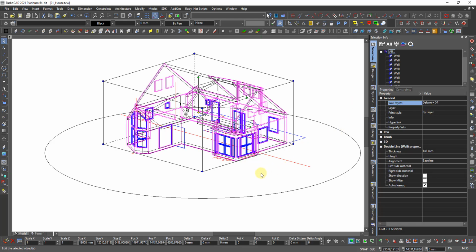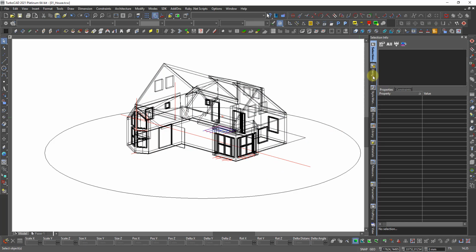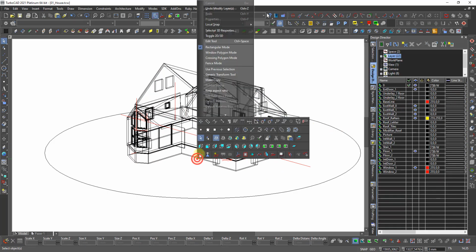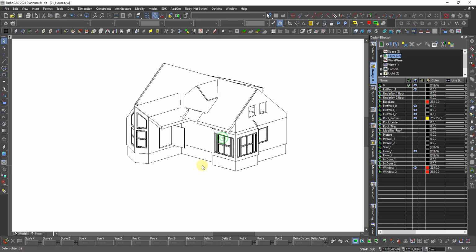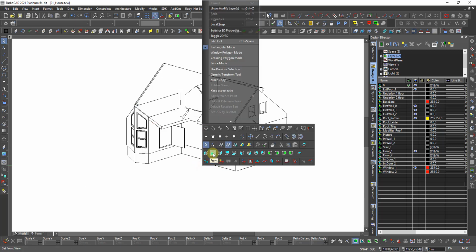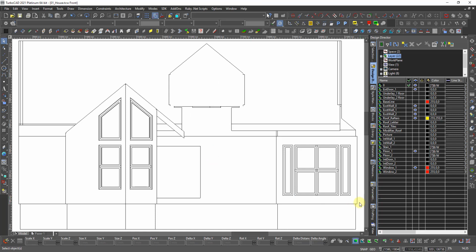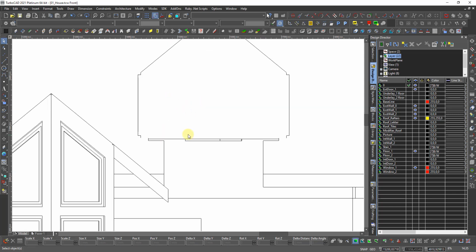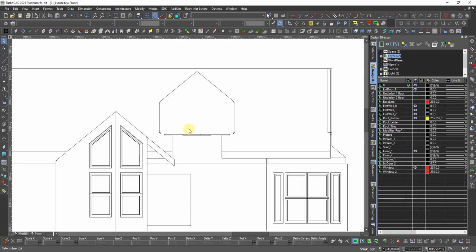So then everything is moved out, and I turn on cell, and I go and say hidden line, and from the front example, you see now it goes 54 millimeter outside the wall itself. This we need to make an opening modifier here to cut out for this.